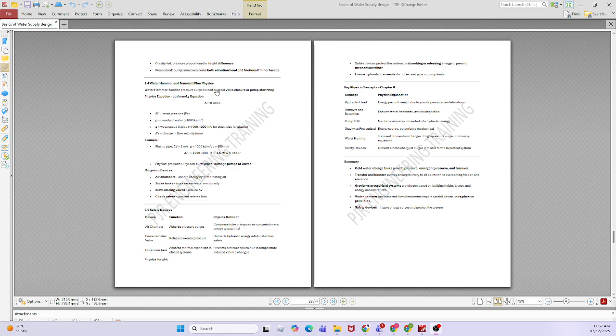Okay, so this is a water hammer arrestor. Why is the water hammer arrestor required? Remember, last time we calculated based on the WSFU, you will choose the model. Okay, but what is behind the water hammer arrestor? There is a surge pressure. That surge pressure will be absorbed through the water hammer arrestor. So how to calculate surge pressure? By using the Joukowsky equation.